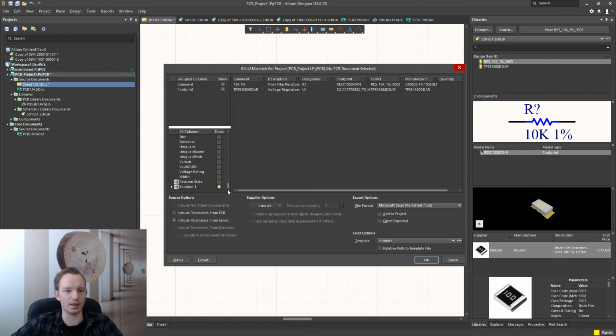And we can also export things like package, casing. Let's see, case, package. Do we have that? Yeah, exactly. So it's 603 SOIC, and there's a bunch of different fields. There are so many different fields. Packaging, I think packaging is more like tape or reel, that's how they package them when you buy a lot of them. Operating supply voltage, pretty cool.